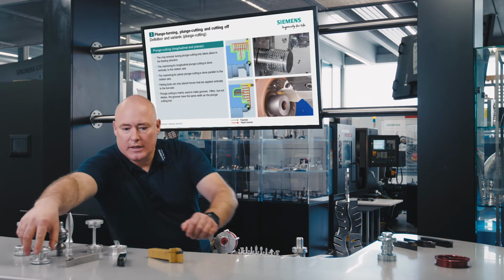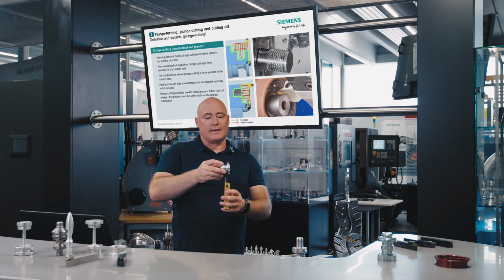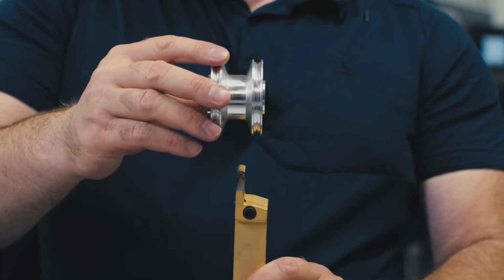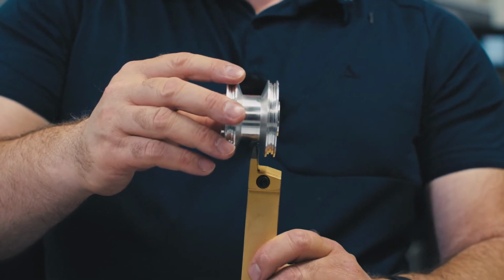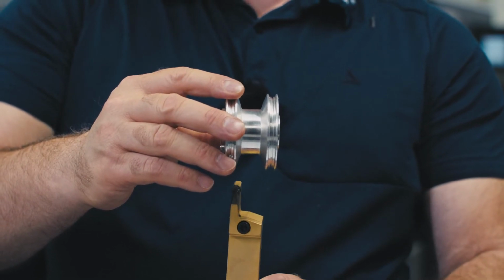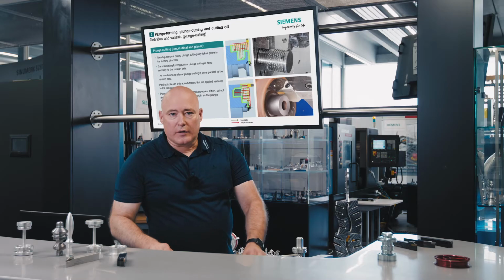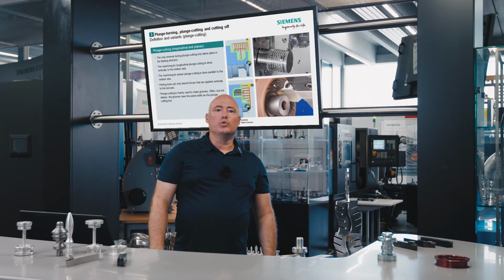Another technology in this field is grooving. In this case, stock is removed vertically in relation to the workpiece axis. That is to say, the tool is fed, withdrawn, moved laterally, fed again, withdrawn again, moved again, and fed again. This process is mainly used for making grooves.